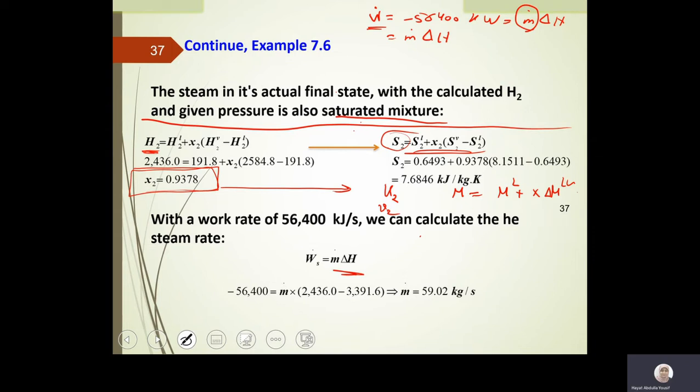The procedure, I will say again, is that you will consider if it is isentropic, and then you will find S1, you will equalize it with S2 dash, and then at the outlet condition, at the given S2 dash and the other property, you will find H2 dash. Then you will substitute in the efficiency equation to get the actual property. Once you get the actual properties, then that is mainly what they need. If they need any other thing, at least the actual properties, you have them at the outlet, so you can fully define the system and find any other properties if needed.